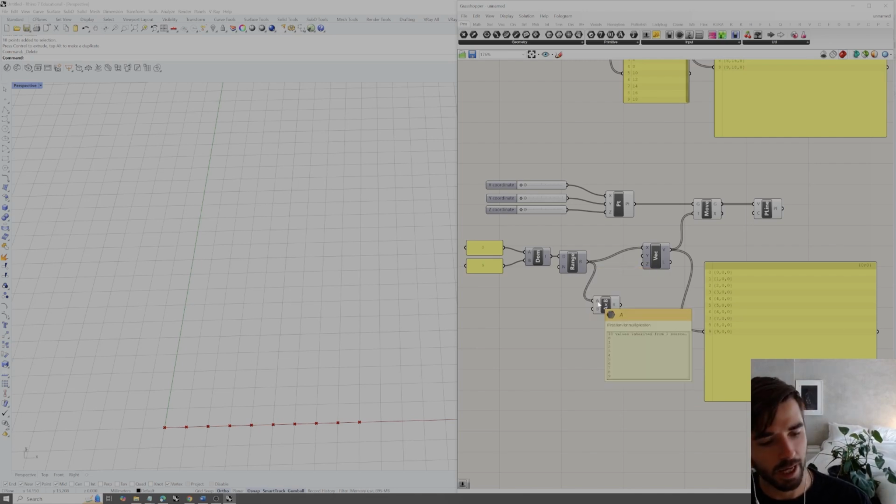That's going to go into the A as a number input, and then the second value will take a number input into the B. So we're going to copy one of these panels and give this a value of 2, so that each one of these inputs, so 0, 1, 2, 3, 4, get paired up with 2, and it's going to multiply each one by 2 to give us an output of 0, 2, 4, 6, 8, 10, 12, and so on.